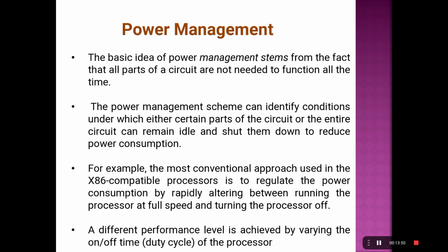Next one, power management. What is meant by power management? Generally, it means some of the devices in the circuit may not be used, yet the complete operation is still going to be performed. At that time, you have to identify such devices. What devices are in the idle condition? You have to switch off the power supply to those particular devices.